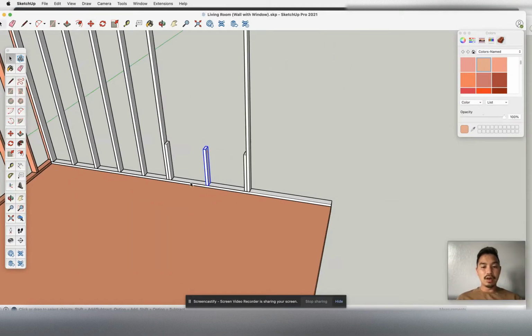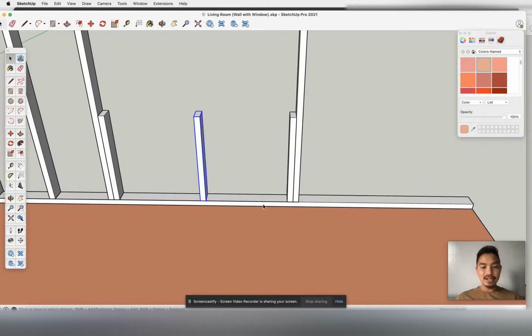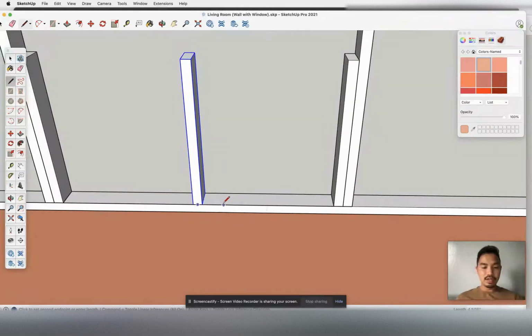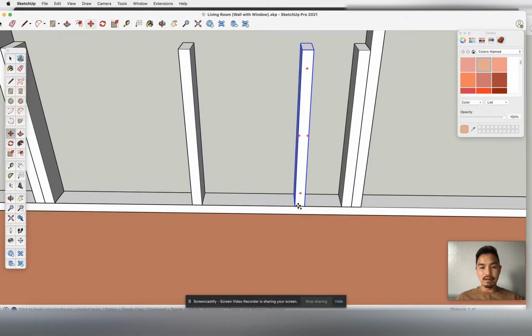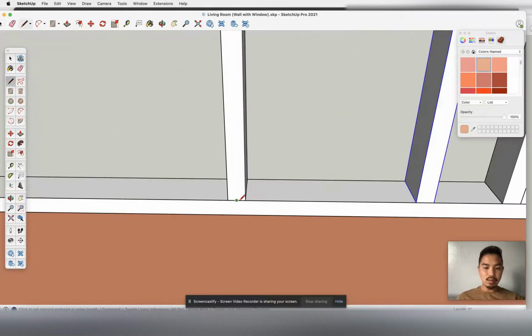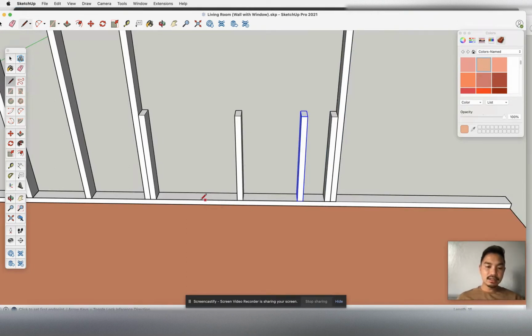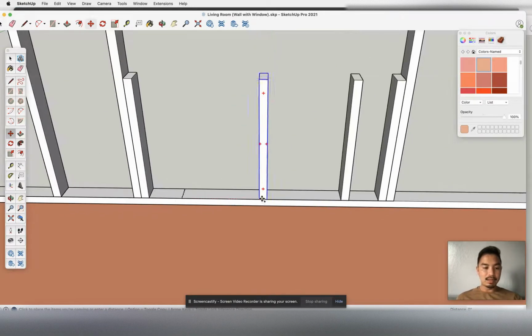There it is. All right, now that we have the center, it will be 16 inch from there to the right, 16 inch to the left. Take the line tool from the center, drag it over this way, 16, enter, find the endpoint, there it is, drag it over this way. That's our first guideline. I'm gonna make a copy of that now. And for move, option make copy, grab our cripple stud, click that, drag it over to the midpoint of that. I will do the same thing on the left hand side. Click once from the center, move it over, 16, enter, find the green, there it is, that's the endpoint, drag it up. Now make a copy of this center of this cripple stud over that way as well. And for move, option to make copy and grab that over.